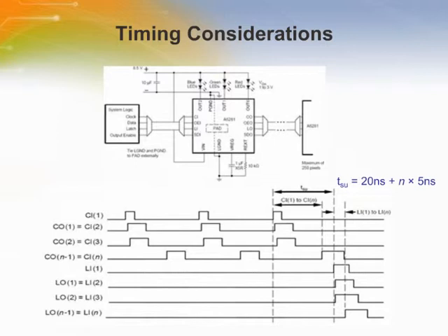After all the data is written to each LED driver in the chain, the data is latched by each driver via a low to high transition on the latch input pin. The latch output pin of pixel 1 drives the latch input pin of pixel 2, and so on down the chain. These signals are buffered and driven asynchronously relative to the clock input and serial data input pins. Therefore, the mismatch in delays between the clock output and latch output must be taken into consideration.